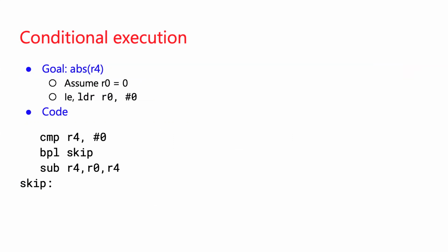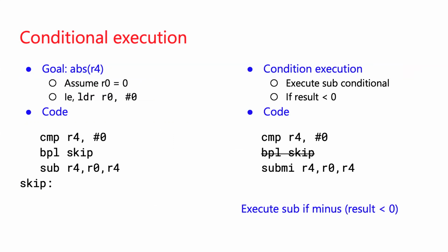All right, I'm pausing for effect because we can do better than this on ARM. Here we've got a 3-instruction solution, but I know we mentioned it, we just haven't seen it until now. The branches aren't the only instructions that are conditional in ARM. Lots of instructions can be conditionally executed. In fact, you can think of the conditional execution of a branch as really the same mechanism that lots and lots of instructions can use.